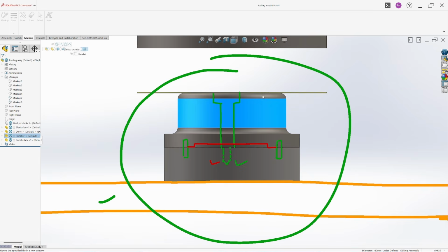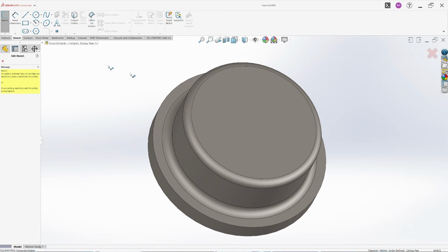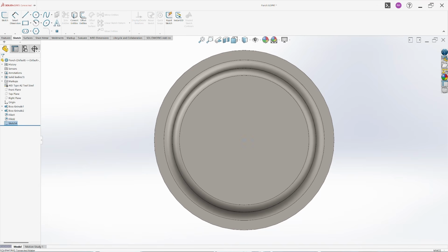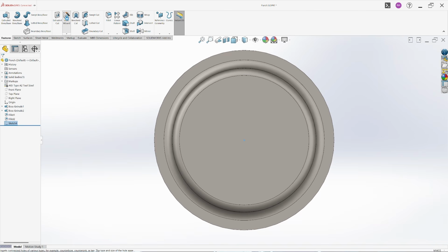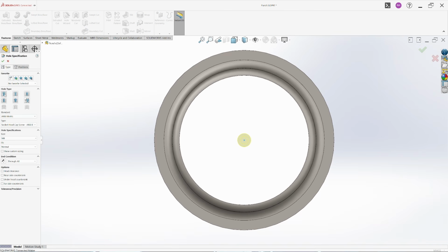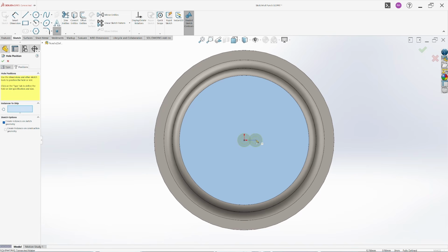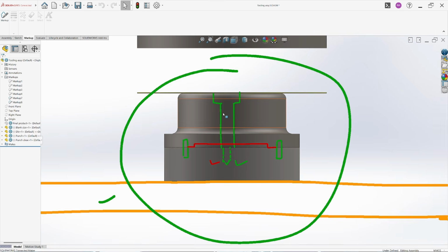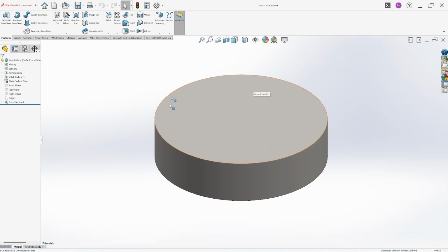First let's open the punch, and let me take a point at the center. Let's close the sketch, choose Hole Wizard from right here and choose counterbore. Here for the socket head cap screw, I'm selecting M8, which is fine, and it's automatically positioned in the new version of SolidWorks if you're using 2025. Let's hit OK.